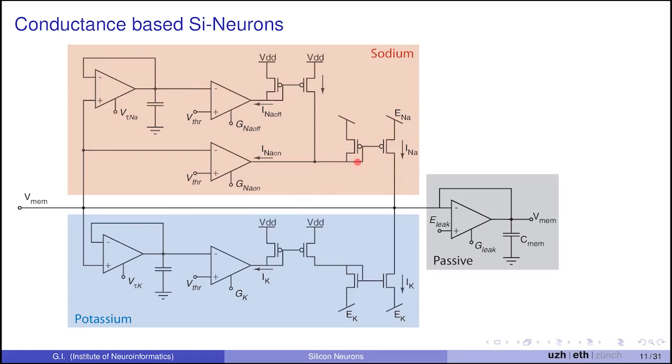And so even though you copy paste identical copies of these neurons, if you inject exactly the same input, you will start seeing slightly different outputs because of these device mismatch effects. And the larger the transistor count, the stronger is this device mismatch effect. So in this circuit that has many transistors, there is quite a substantial device mismatch effect.